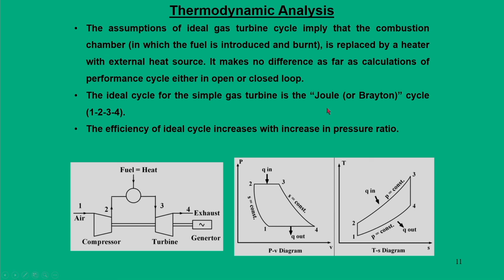So, what you see is that when the cycle goes from state 1 to 2, it is a compression process. So, it is an isentropic process. Process 2-3 is considered as the heat addition process, 3 to 4 is the expansion in the turbine, and 4 to 1 is the exhaust process. So, here it is drawn as a cycle because more or less point 1 coincides with point 1, although the cycle is open in nature, but the way we represent it resembles the closed cycle